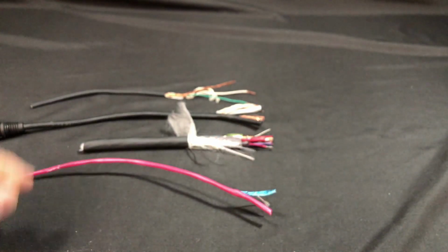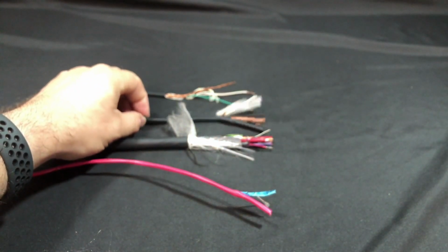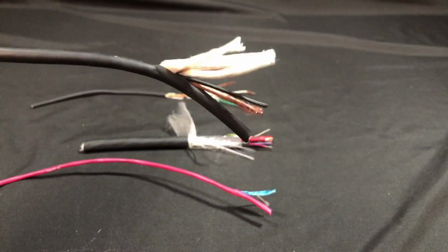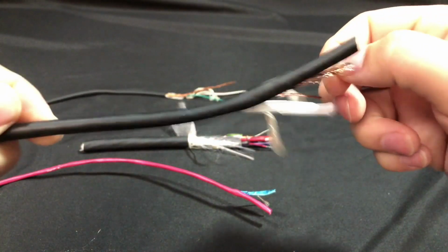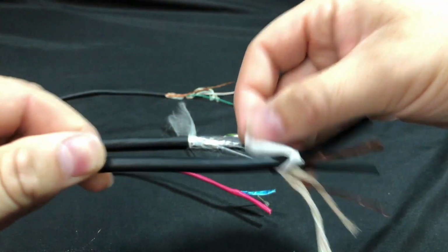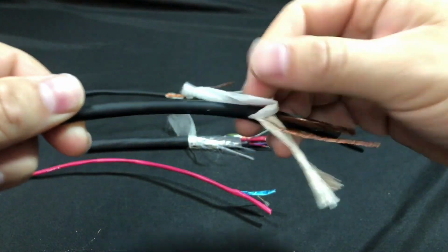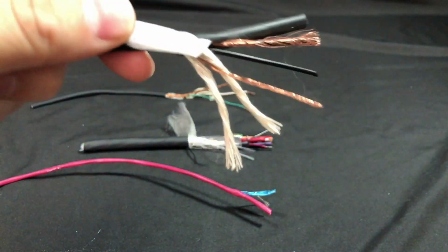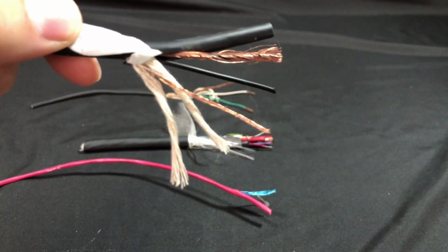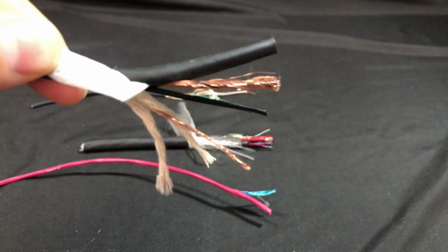Another thing with these cables, you may be wondering, why don't the microphone cables have the foil shielding? Well, microphone cables typically are going to run low impedance signals, which means they're going to be less susceptible to that turning into an antenna effect due to capacitance, because they're going to have low impedance signals. So foil is not super necessary because it's not really going to be much of an antenna.